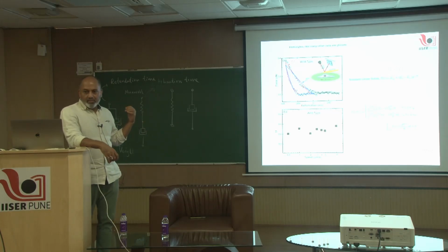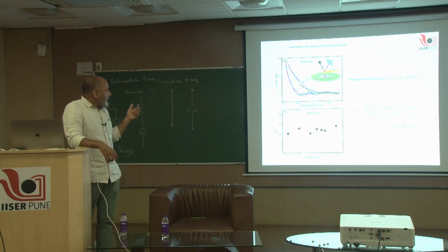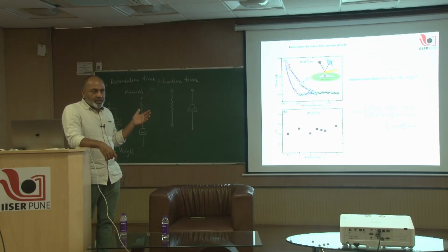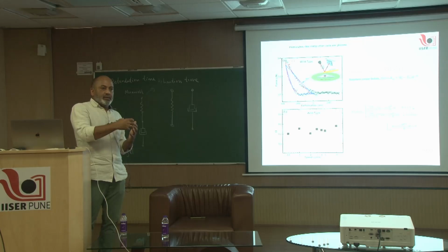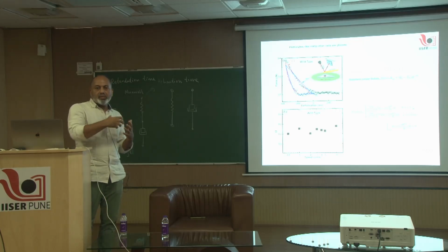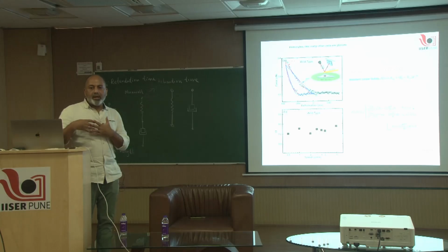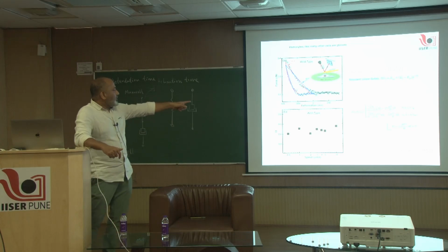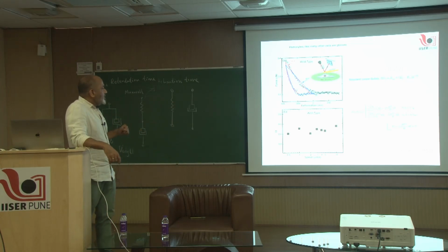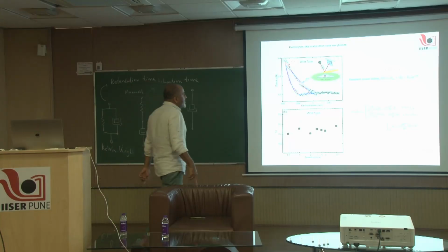And this is something called Ting's model. This is from Ting's paper, and there was a paper before that, something close to the 60s, in mechanical engineering. What it is telling you is that if you are deforming a material with a history, with a certain rate, and the time is not held constant, or the material is not held under stress, you progressively deform and come back, how should the material behave? That equation that you see there is Ting's equation. In that you can place your constitutive model.